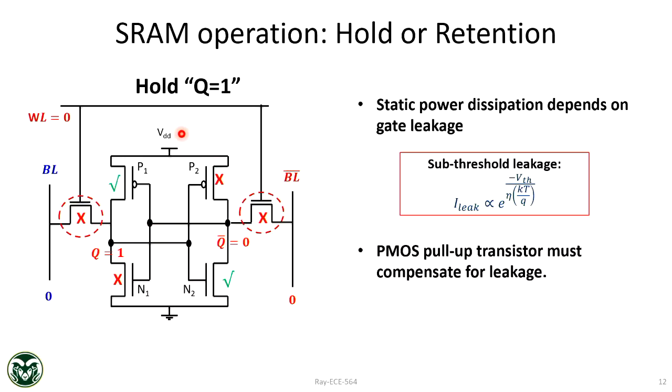It can be 0.1 volt, 0.2 volt. And here you have to worry about the extreme cells, because of one bit flip. Think about your FPGA configuration. The FPGA configuration memory is SRAM. One bit flip will mess up your entire configuration memory. So this is an extreme value problem. There will be median cells which are good. Every median cell is fine at 0.1 volt. They can keep the data.